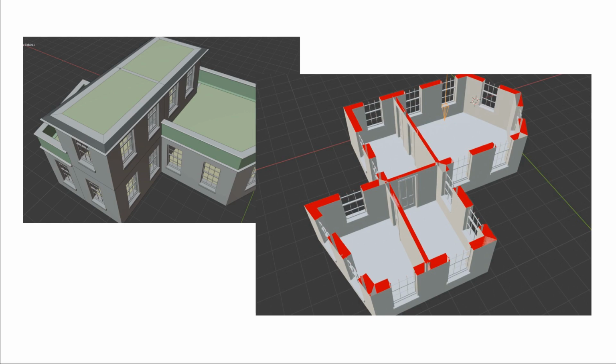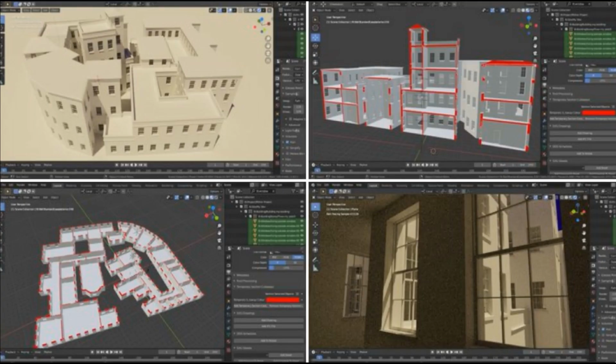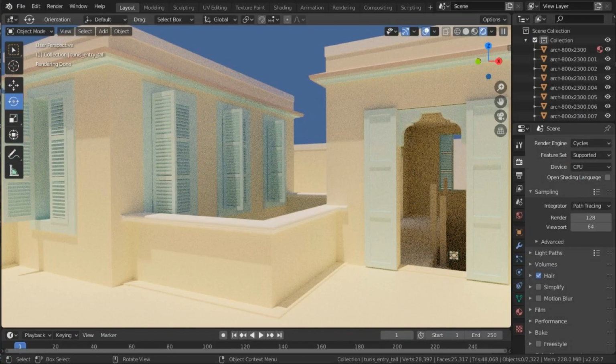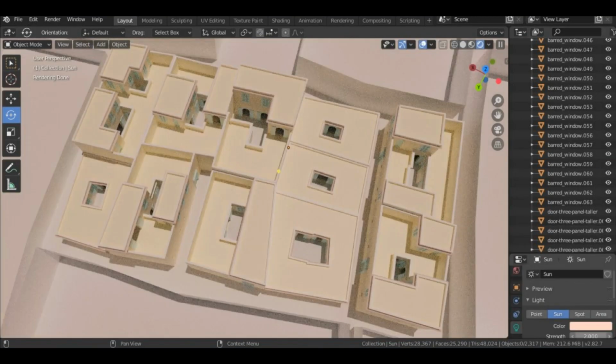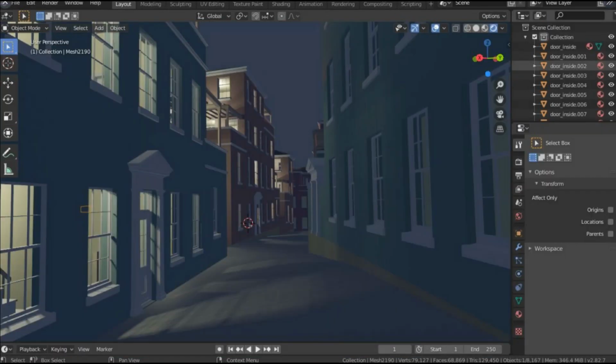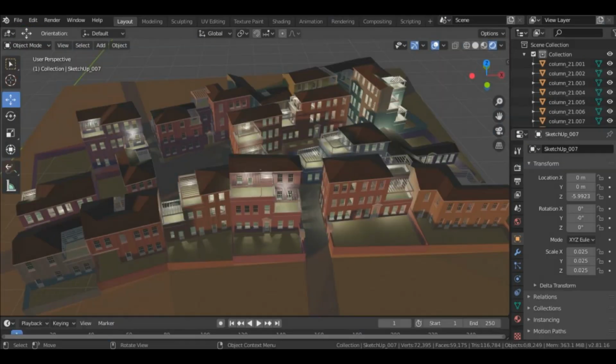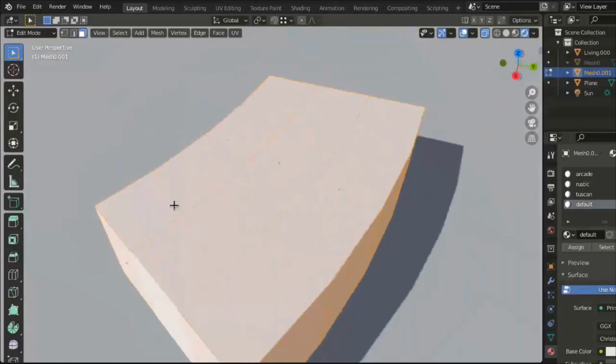So everything you see here, all the resultant spaces know their spatial functions. All the walls, doors, and windows are all stored in the native IFC data. You can then pass all of this through an evolutionary solver and start scoring spaces with respect to arbitrary values. In this case, the software known as Homemaker scores these spaces based off architect guidelines in the book A Pattern Language. And the software we're showing here combines 3 free software.